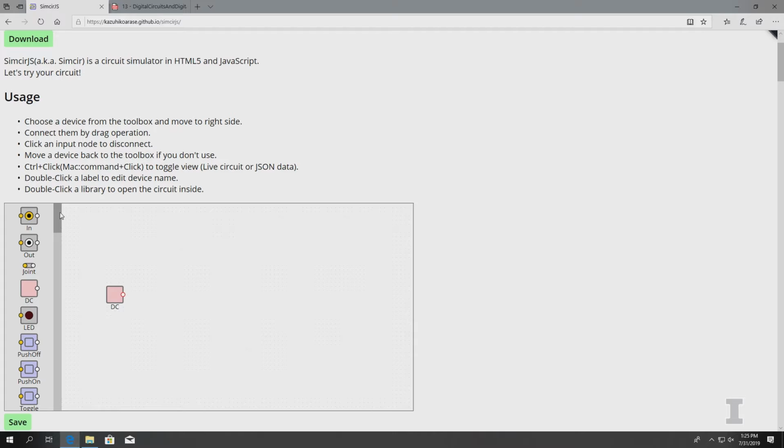And then grab an LED light and bring that into the sandbox as well. The way you want to do it is, when you click on those little circles, you click and hold it down, and that's like dragging a wire. And if you click again on it, it'll make it disappear. So you click and drag to wire it, and then you click on it again, and it disappears.